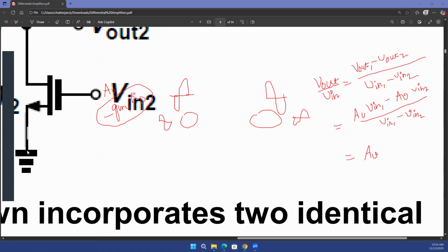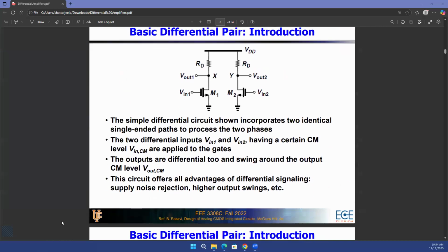All right. So what is the other assumption that we made here? That the gain of the left side branch and the gain of the right side branch are exactly equal. And only in that case, you can take that quantity common, right? So can it be a scenario that the gain of the left side branch and the right side branch are not equal? Of course, it can, because what is the gain? Gain is going to be GM times RD. So RD is this term.